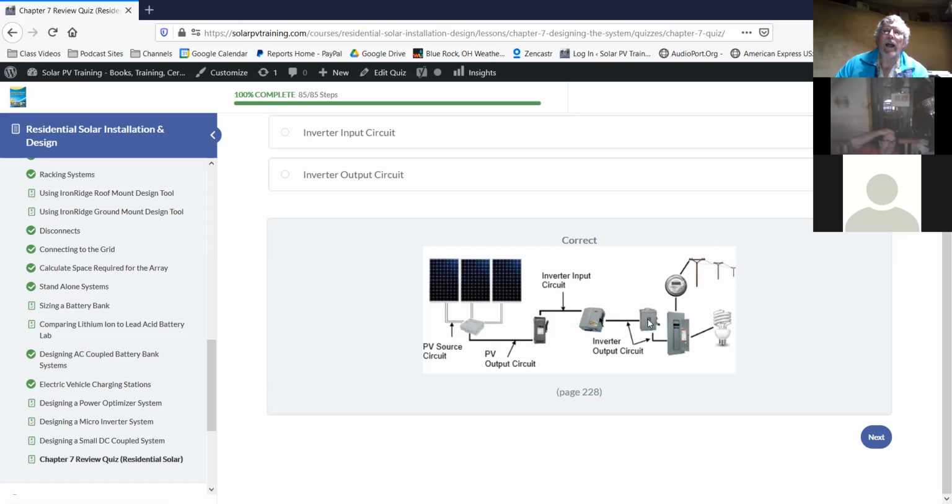So then they look around, and it's got to be within visual sight, within 10 feet. They'll see this AC disconnect, and this will say, main photovoltaic disconnect, and it needs to be externally operable so they can just pull the arm down, turn it off. So that's where the location requirement comes from.